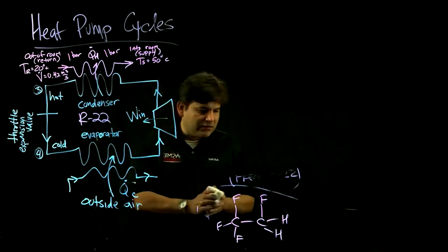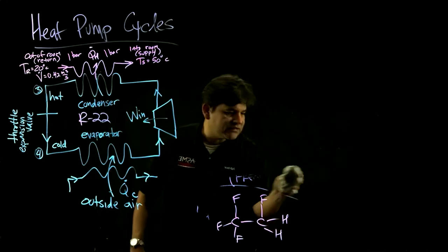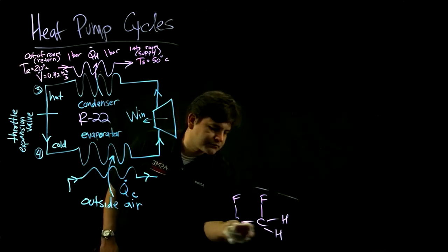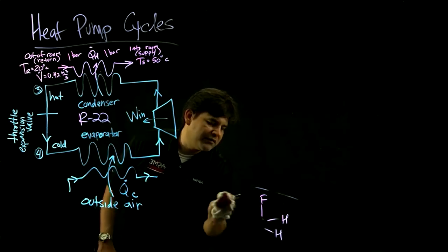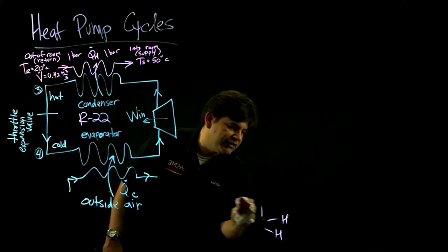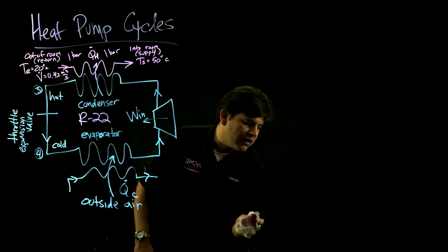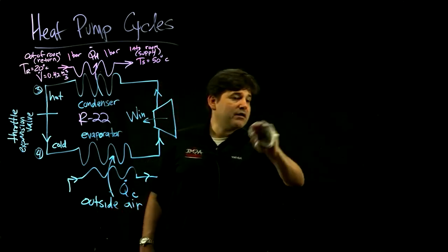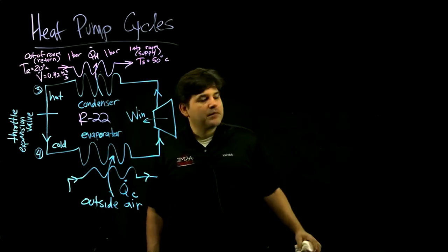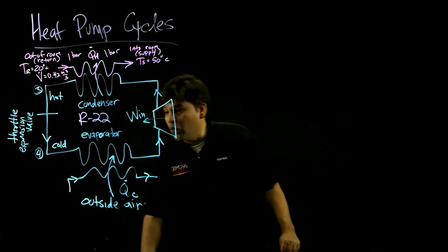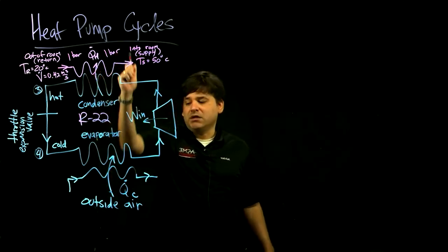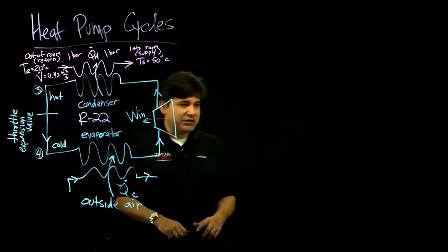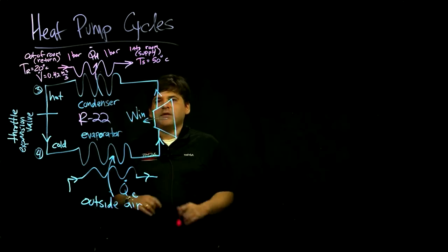And by the second law of thermodynamics, to run this heat engine in reverse, you have to put some work in. There's not going to be any work out. In reverse heat engines, there's no work out at any stage, but there is work in required. For a heat pump, you want the heat out as your application. For a refrigerator, you want this QC of the cold space as your application. And that affects the operating parameters.